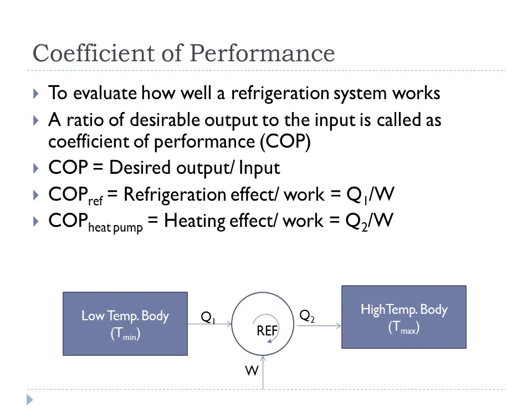On the other hand, we also see that Q2 amount of heat is rejected by the refrigeration system, but it is supplied to a high temperature body. Suppose our purpose is to heat up this high temperature body. If we want to maintain the high temperature of this body, we need to supply Q2 amount of heat to it. So if our desirable effect is supplying heat, then the same system will be called a heat pump, not a refrigerator.